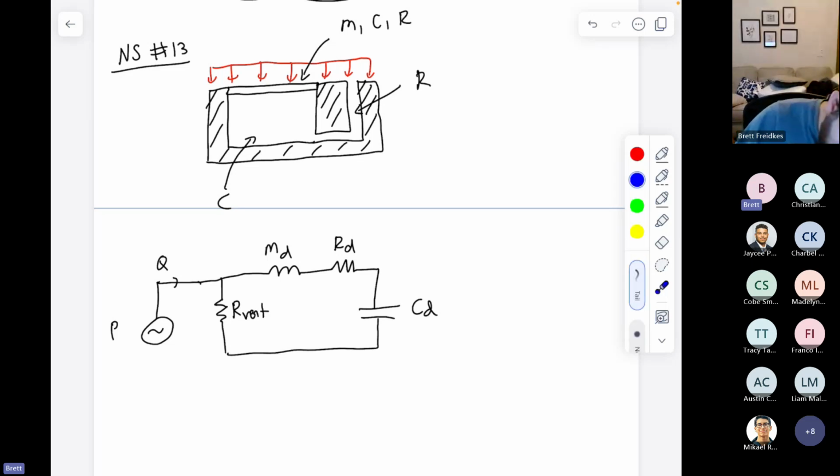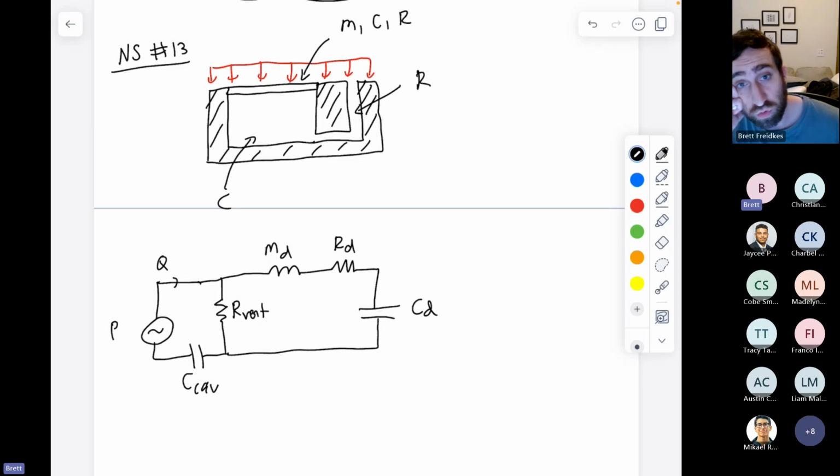And then they both meet inside of the cavity. We see that the diaphragm will deflect into the cavity, and then the vent will allow volume velocity to go into the cavity. So because they are in parallel, they'll end up meeting again and both enter the cavity, which we're saying is just a compliance. And that was our acoustic circuit model of a microphone that looks like this, where it's simply just the diaphragm, a vent, and a cavity. Is that okay? This should be review.